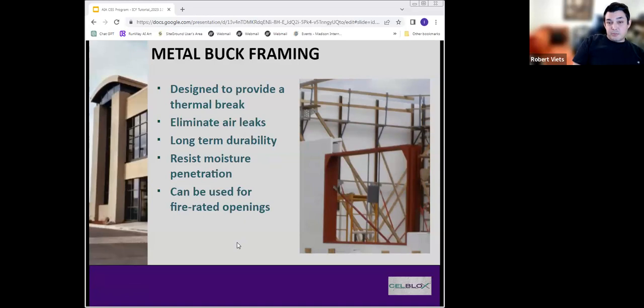They're also designed in a specific way to eliminate thermal breaks. They have a thing here that eliminates thermal breaks, which is nice. They're also fire rated, so that's another pro. The big one for commercial jobs is that they're fire rated. Other than that, though, I'd kind of stay away from the metal ones.